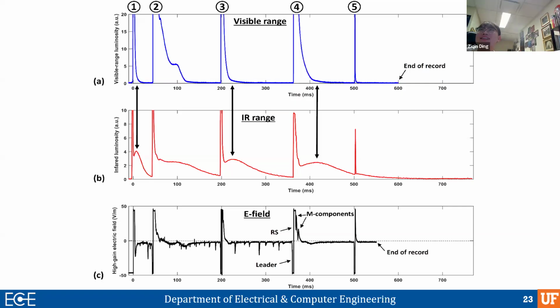Yeah. So the interval time just tells you the maximum exposure time, but then you can control the exposure time yourself, right? You are correct. For the UV you are talking about, the maximum frame interval that I just showed is 66 microseconds. That is for the high-speed camera, and for the UV intensifier, we gated at 50 microseconds. So in other words, we're only looking at 50 microseconds inside that 66 microsecond frame interval.